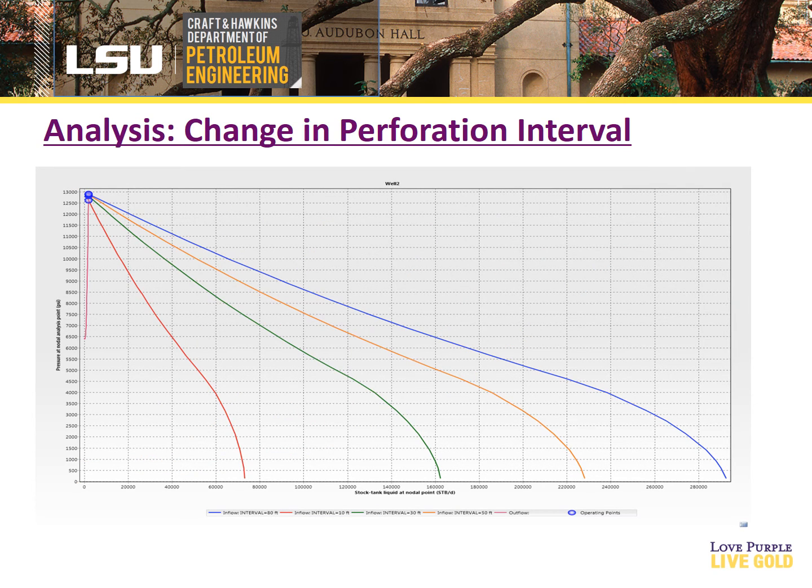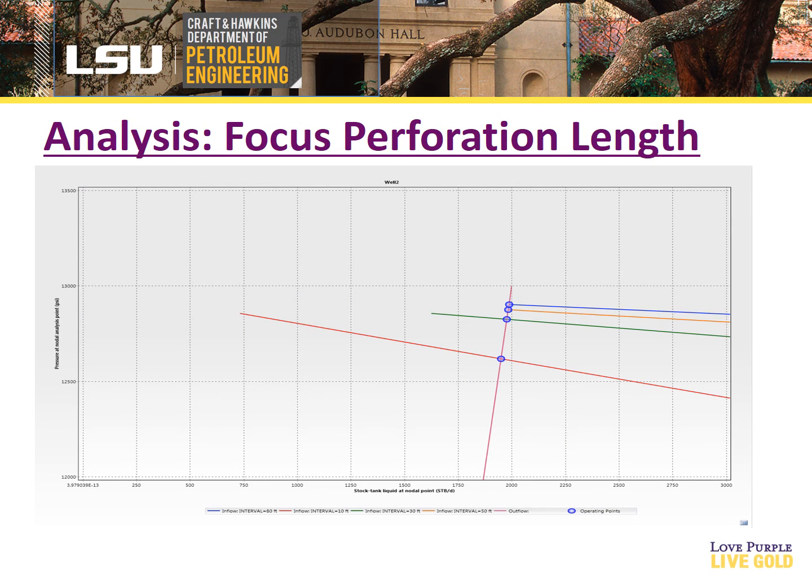This graph represents a change in the perforation height discussed before. While the perforation height may not greatly affect the depletion time of the reservoir, it has a large margin of change in the absolute open flow potential of the reservoir. This is a zoomed focus to show the TPR of the previous graph. Similarly, the flow rates change very little due to perforation height changes.